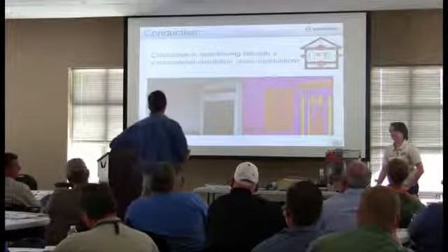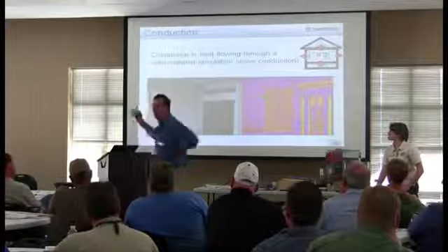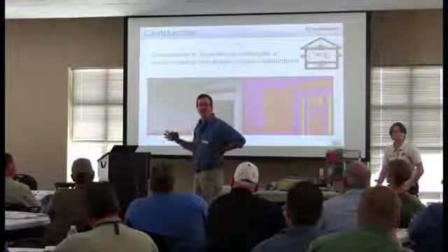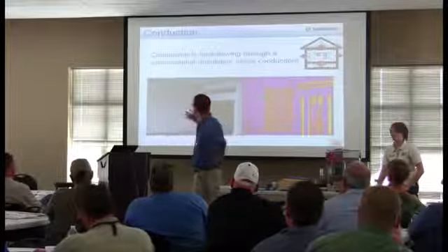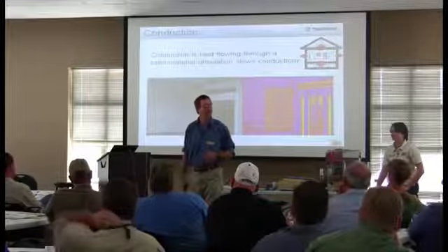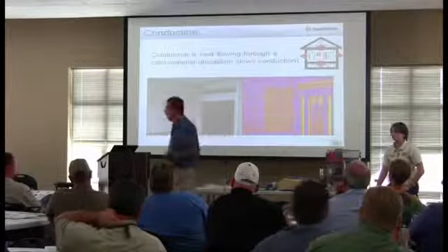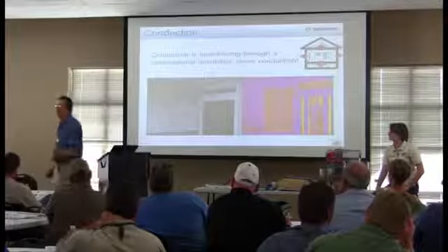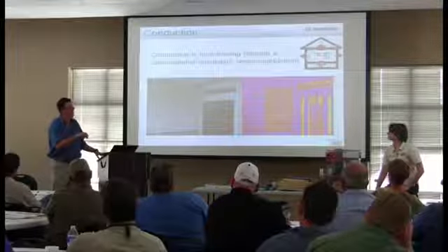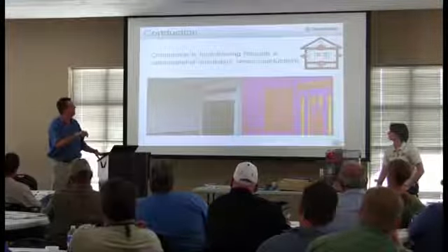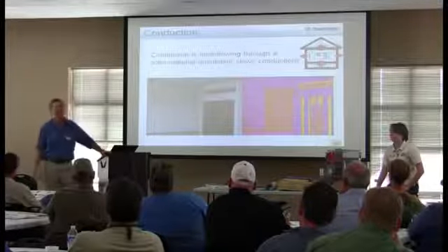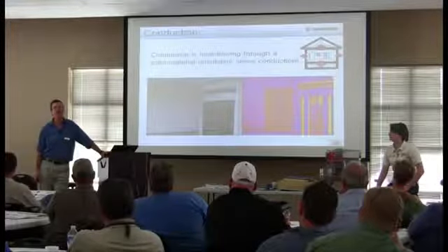It's possible. A good theory is that the tub was set against that exterior wall during framing. The tub gets set before the insulation, right? And once the tub surround is up against that wall and there's sheathing on the outside of the wall, it's kind of hard to get insulation in there. We don't really know what happened, but we can definitely see the effect of missing insulation. The effective R value of an empty stud wall is basically the same as this transom window up here. So that's pretty bad. Maybe an R2 or something like that.